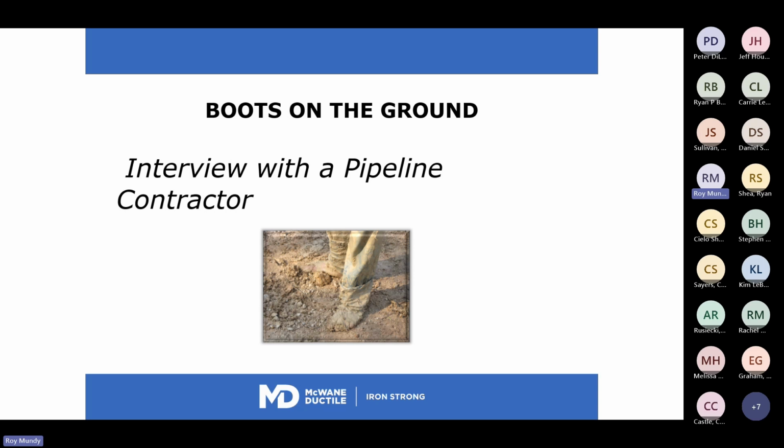The reality is, however, many times, even though I'm going to get a lot of positive indication in terms of the quality, resilience, and sustainability of ductile iron pipe, before I could leave the room, there would be a but. But we can't afford ductile iron pipe. Ductile iron pipe is virtually twice as expensive in terms of price per foot than PVC pipe.